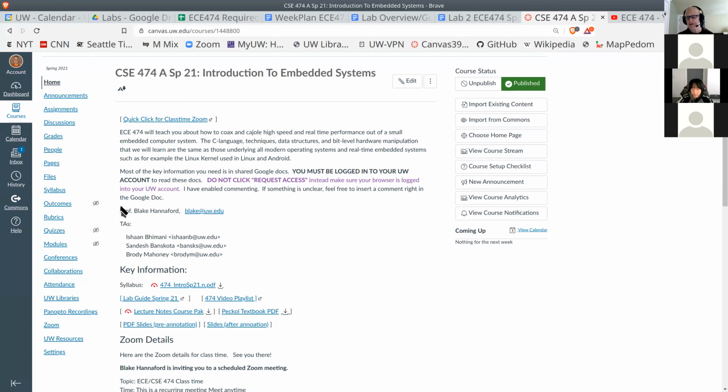But that's not a scalable solution that really lets you engineer a product. And the first way that breaks down is when you want the Arduino to do 3 or 4 things at the same time, which is usually what you want in a real product. So in that case, you wire up 3 or 4 sensors, you download 3 or 4 software drivers, and you merge them together into an Arduino sketch, and it doesn't work. And the reason is that each one is based on different assumptions. And then the high school kid is typically in worse shape.